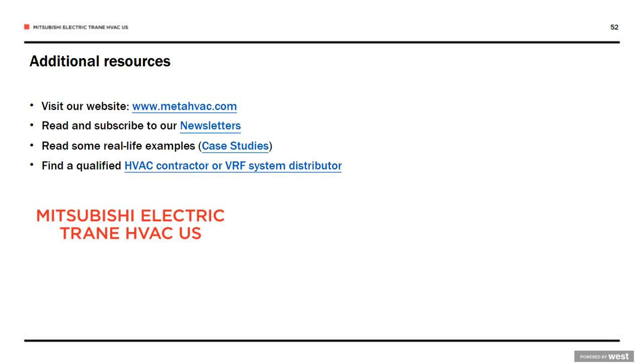Yes, we see that, I don't know, how do I best explain this? Sort of the same way that I answered the last question. If we can bring in, say, 55-degree air in the shoulder months using DOAS, we'll do that. We'll bring in 55-degree air because it's, in essence, cooled for free. And then allow the VRF system to trim it out, whether it's a little bit of heat or a little bit of cooling. So it's not that uncommon.